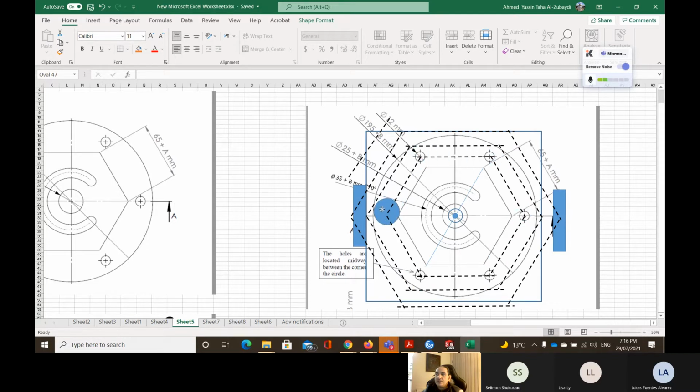Okay, now we have taken it to -4 millimeters. We need to remove more, for example, if the height is going to be 5, we go up once again to Z equal to 5. Then we fly to this one with G00. Then we go down and repeat the same process, but Z in that case is going to be equal to -5. And thus we clear everything around the hexagonal shape.